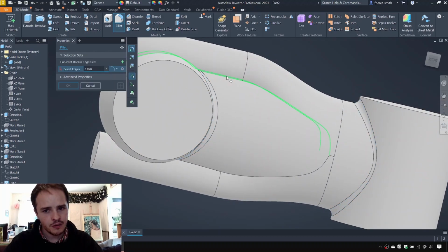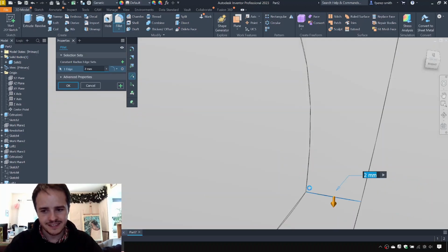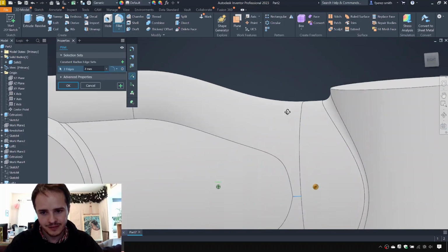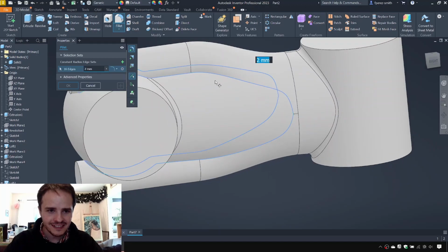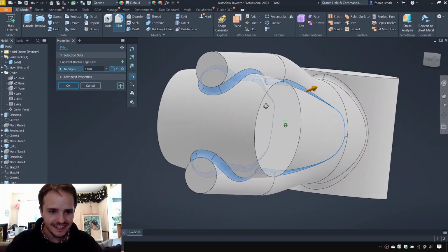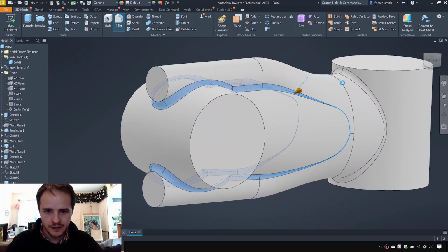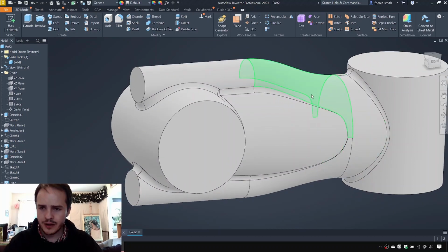And hit the plus. And now I'll add in a fillet. Ooh, we might need one in there. Not too sure how that will work. We'll see. We'll add in a little fillet there. Oh, I think my Inventor's having a heart attack. We might have a manifold surface. All right. Yep. Hit plus. It didn't wig out. And now we can add in a fillet in here. Yeah, there we go. And we've got a nice, neat 2mm fillet that goes all around. Looking very nice. Wonderful. Okay.